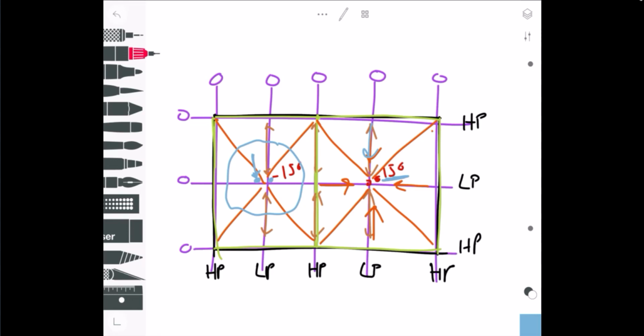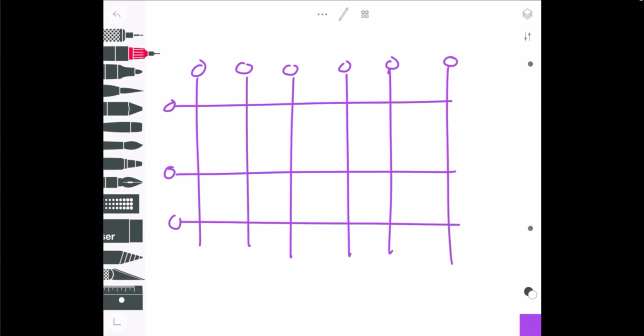So what that ended up doing is making some of the, if you have a larger grid bay, like 9 meters plus, then you might not quite reach that 2%, but it's okay. The roofing manufacturers ask for 2% as the ideal, but if it's 1.25 or 1.5, whatever, it's fine. Just be clear about it on your drawings as to what it is, so that when the roofing manufacturers are bidding on the project, they know what it is and they don't try and weasel out of the warranty because of a lower slope.